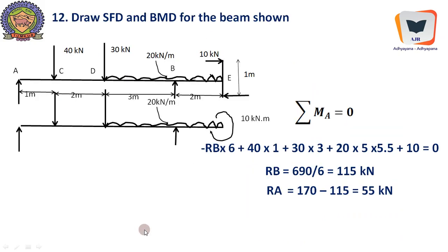So we'll go for the second problem. Here the problem is a little complex, in the sense there is a concentrated moment applied at the free end, and this concentrated moment is not being applied directly, and there is a frame welded to the beam, and there is a couple that is being applied, 10 and 10. It generates a clockwise moment at this particular junction at the free end. So even the free end will also rotate due to this free moment of a couple.